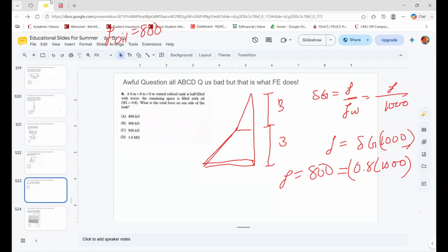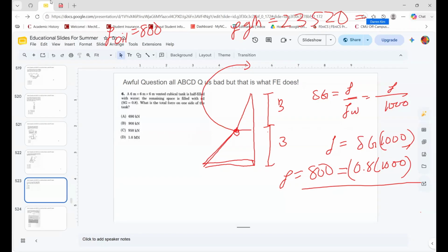So here's what we're going to have to do. Because we have density here, we're going to do rho g h over here, max the P1, whatever rho g h is. So 800 multiplied by 9.8 multiplied by 3. And that gives you a max output of 23520. So we're going to say P oil, and it's oil. Over here, we have the max for all of it.